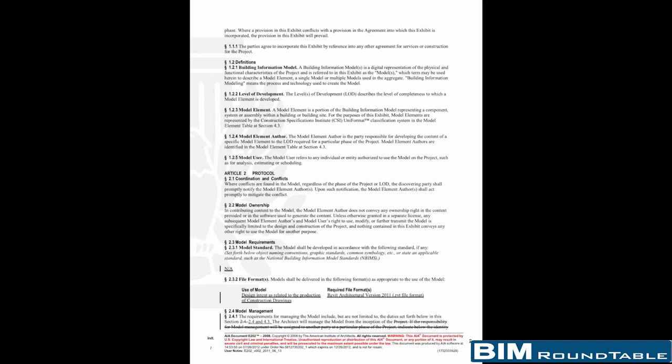But even within 2011, what version it's in as well, I know there are different updates, 11.1, because my understanding is all parties that are working on a model have to be the same. Yeah. Used to be up until 12, though. If somebody worked in a newer build, saved it, and somebody else was working with a non-updated version, it would corrupt the file.